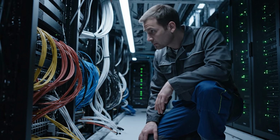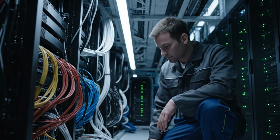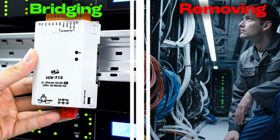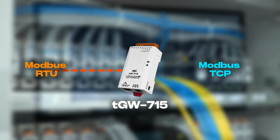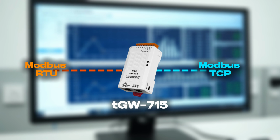But replacing all those RTU sensors isn't an option. They work, they're stable, and swapping them out would cost a fortune. So instead of removing them, engineers just bridge them. They take the Modbus RTU data from RS-485 devices and convert it into Modbus TCP so the facility's monitoring platform sees everything as a modern Ethernet system. And this is where Modbus gateways come in.